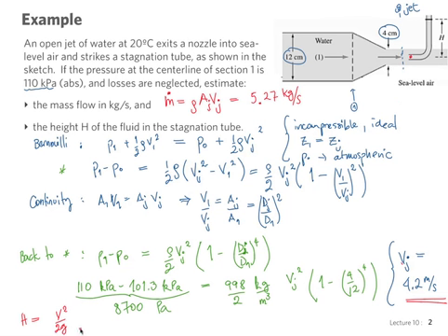You could be precious here and add 1/2 of the diameter, but it's a very small contribution. So you could add the radius of the jet, if you want. It would be correct, and it'll give you a little bit of a difference. And what I get here for that final result, with the radius of the jet, which is 0.02 meters, is 0.92 meters. So you see the radius of the jet did give a very small contribution there.